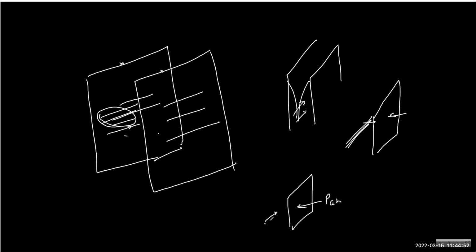But because the air is blown this side, the ability to hit the wall of the paper because of the forward inertia will diminish and this pressure will become P less than PATM. And the same thing will happen for the other paper. So this side is PATM, but inside is P. And because P is less than PATM, because of the blow which you created, they will be pushed towards each other. Understood? Yes or no? Yes, sir.